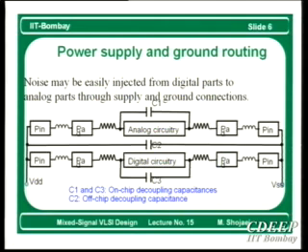In fact, we have filling rules: the density of metal 1, 2, metal 6, metal 8, or metal 12, whatever number of metal layers we have, should be more than some value. And to satisfy this value, you can just put a lot of dummy capacitors between VDD and ground.